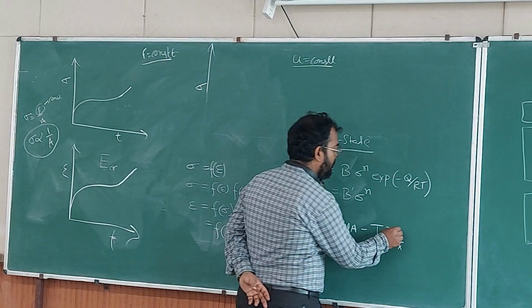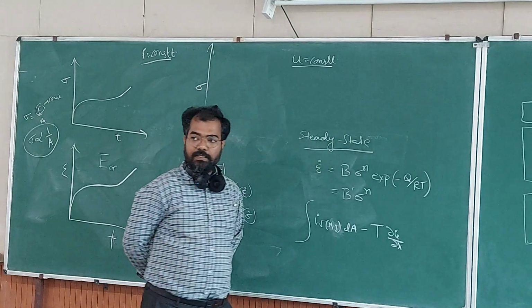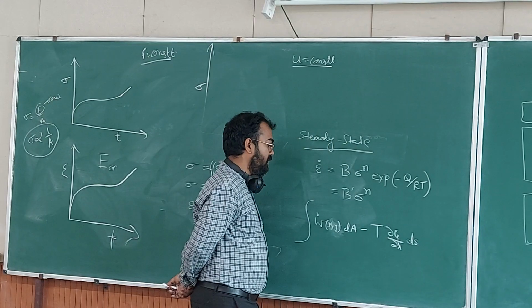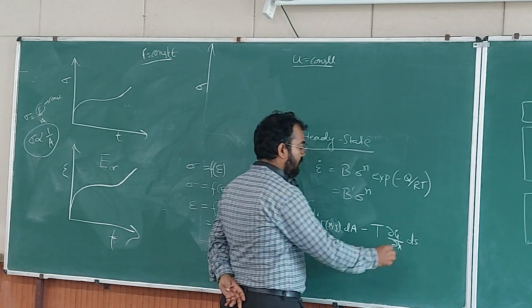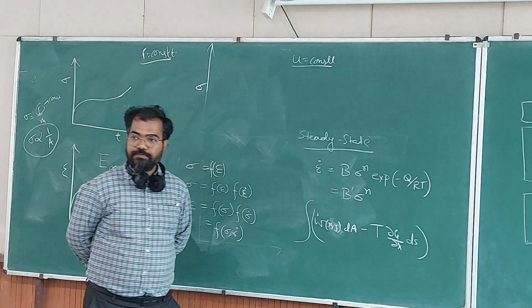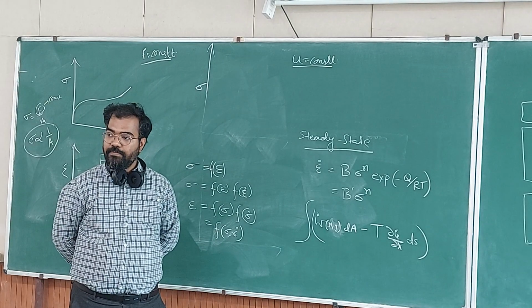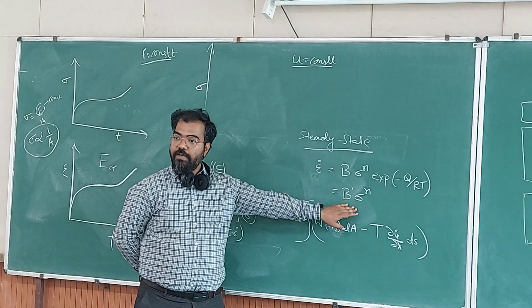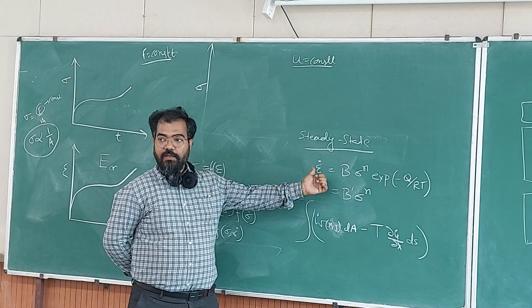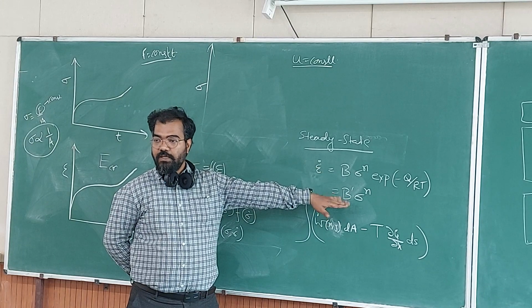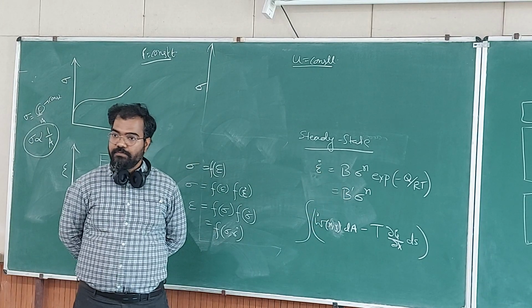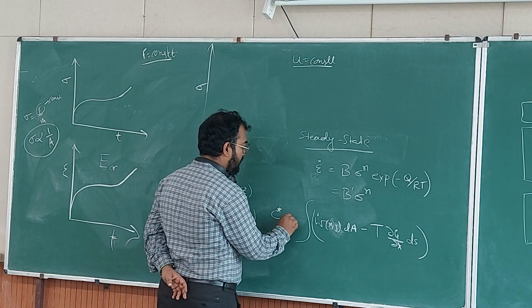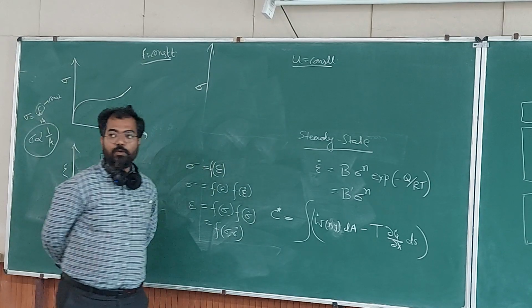Okay, so then you make del u dot by del x, and then you take that integration along the small element of the line, and this becomes a new integral, and this should be path independent. Why? Because this and this will always give you one value. So for one value of strain rate, you will get one value of stress, and vice versa. Okay, so this is designated as C star, a new name.